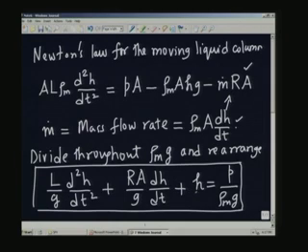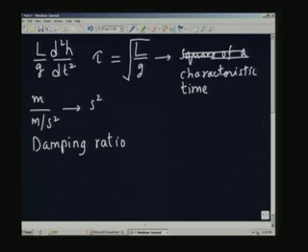Of course, the spring constant is not appearing here because in this case I have L by G which has gone into this particular thing. So, you would have had a spring constant coming in the term corresponding to this displacement term. So, the three terms here: this is the acceleration term, this is the damping term, and this is the spring term, and the right hand side is the forcing function. So, the analogy is very complete, and what I am doing is I am going to just introduce the damping ratio, which is usually given the symbol zeta.